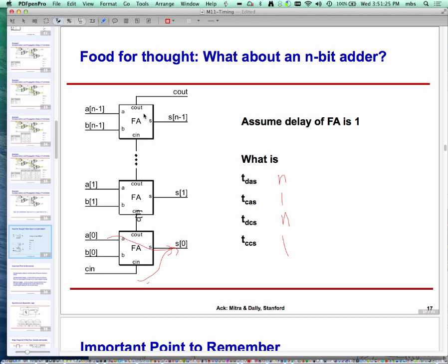And then it becomes really problematic, because you have to somehow find out what the really fast paths in my logic are and take care of them. So it turns out currently in design, when we design these, these fast paths, the contamination delay is not serious. So anyway, we'll continue this discussion next lesson.